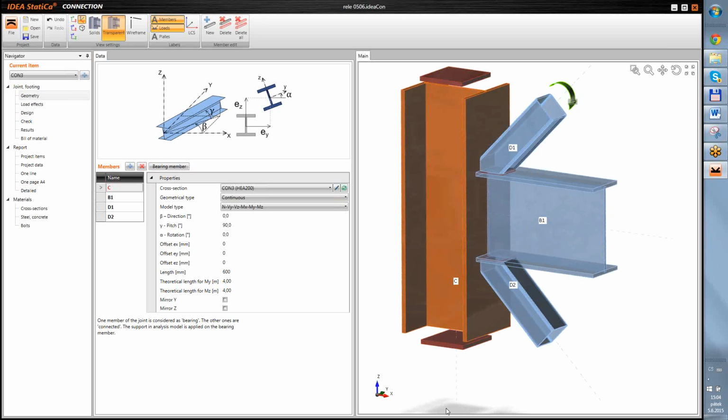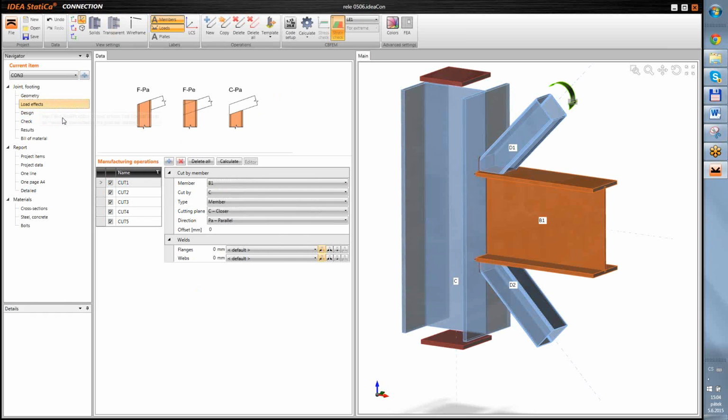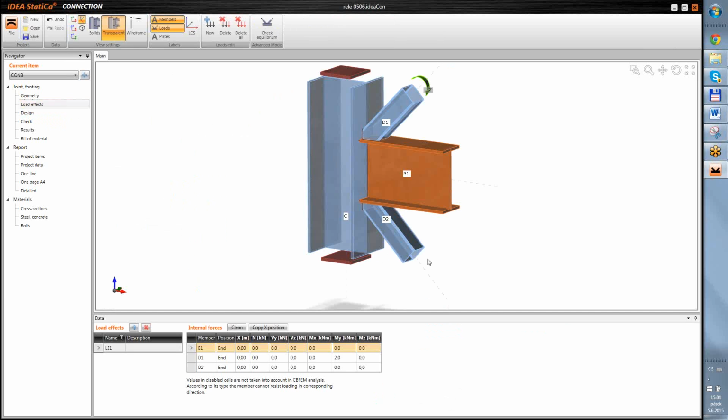Suppose I model this in a finite element program, I would have to put the supports on the edge of the flanges and also on the edge of the web. Does it mean that there are all fixed supports there? Because that's a question I get a lot. Yes, it's fully supported. In fact, we support the section of the member.